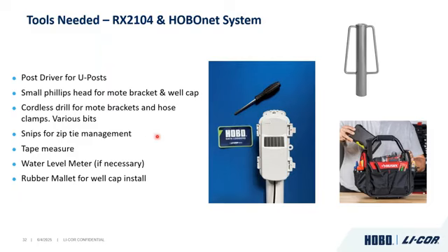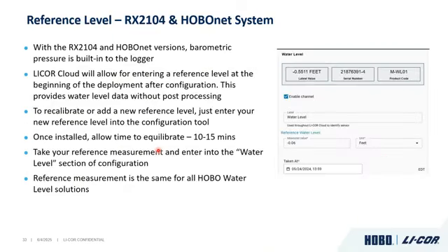Tape measure, it's handy for water level measurements or to measure your length of cable. Water level meter if you're doing groundwater wells and you need a reference measurement, and then a rubber mallet again for that well cap install.